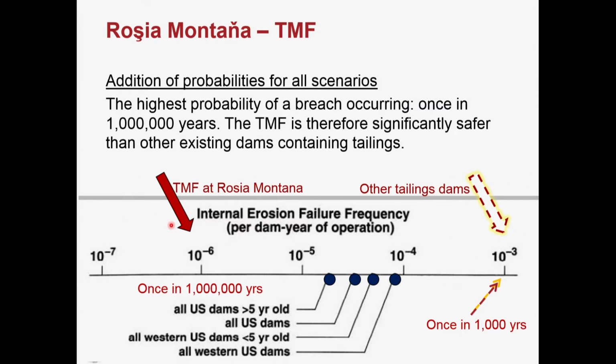So this dam is much safer, but again, the slope was 1 in 3 on the rockfill side and 1 in 2 for the starter dam, and it had very high quality rockfill. But then you can ask me, why did Mount Polley fail? That was a tailings dam. How can that fail? Well, there was an expert group. The failure happened in August 2014, and the panel completed its report in January 2015.